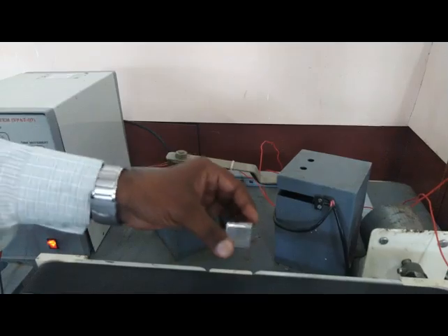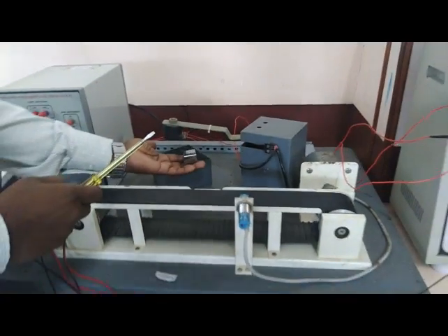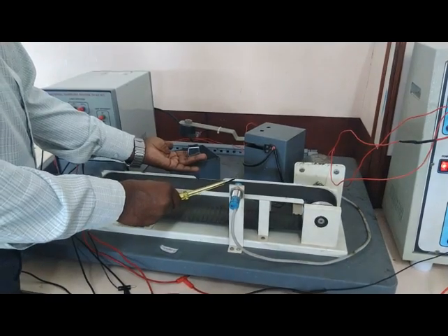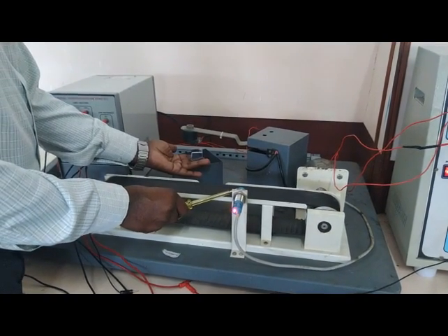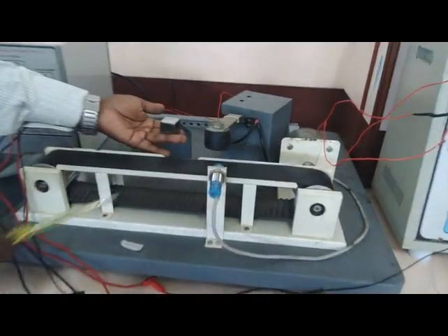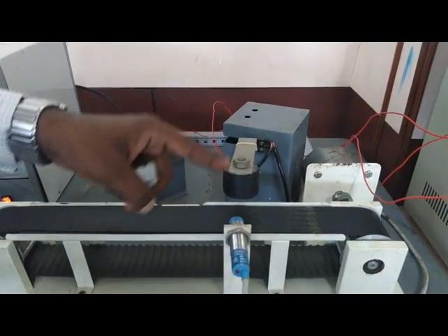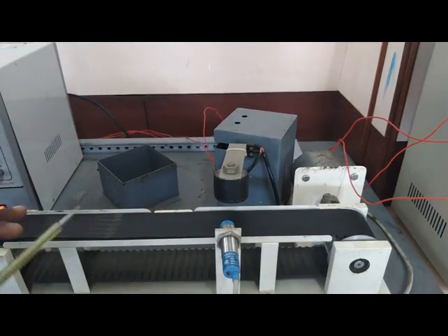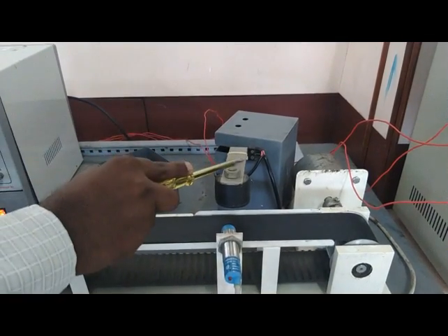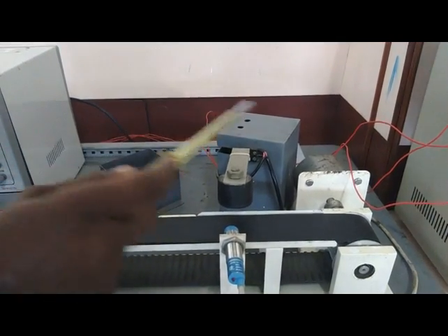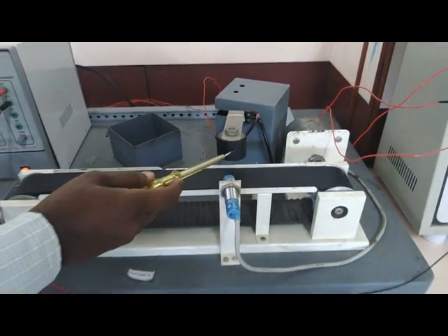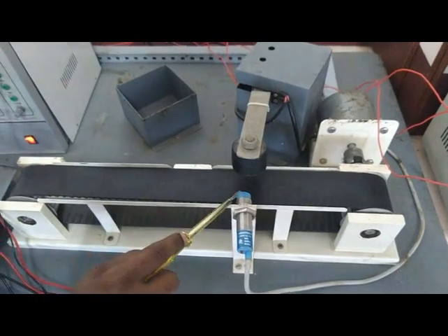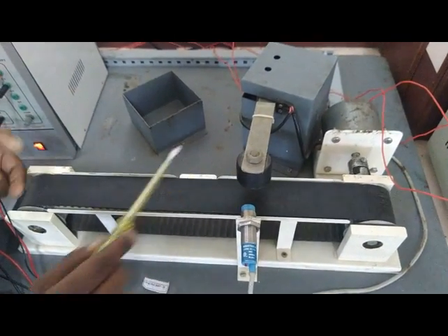Similarly, let me demonstrate. I will keep my material here and enable the proximity sensor. See, it will not pick any material. Only when it reaches the position will it start picking. In the third run, we developed the program so that the arm should move in trigger, and the end effector should go high only when the material is available here. The material is not available, that is why it is stable now.